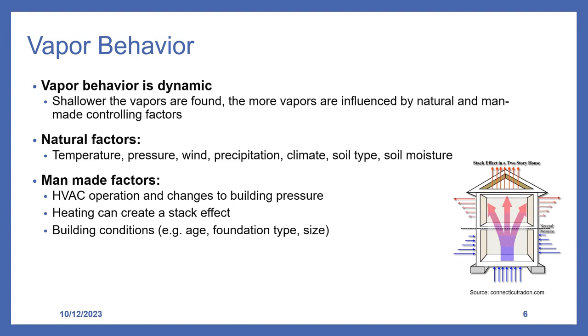Heating can also cause something called the stack effect, as the hot air rises within a building, which can draw subsurface vapors into a building. Lastly, building types, their condition, foundation type, and foundation condition can either hinder or enhance vapor migration.